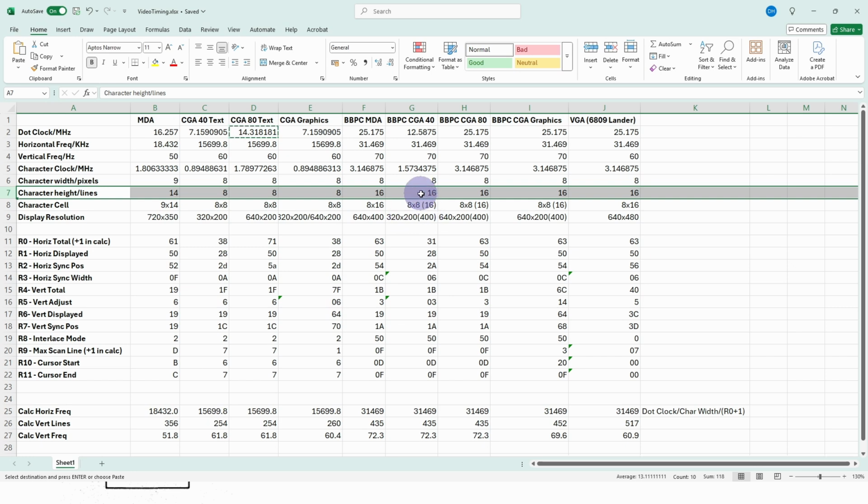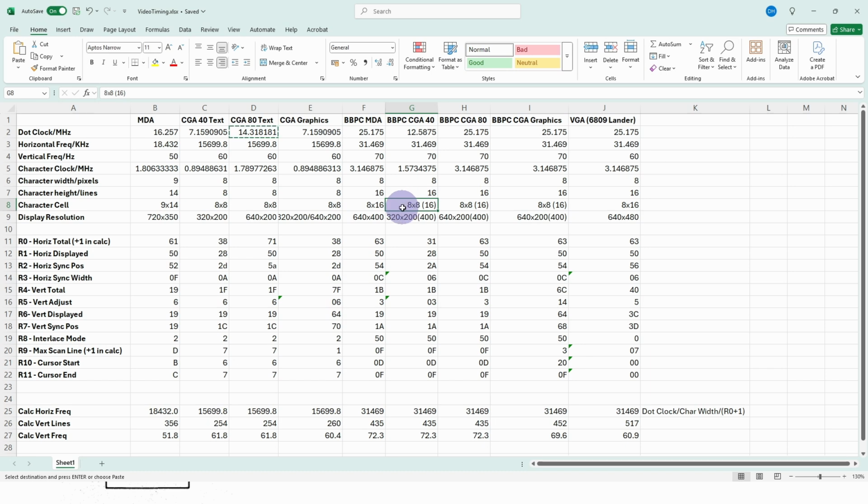By ignoring the RA0 line and only using RA1, effectively we double each line up. So although the ROM only has 8 lines per character, when they come out on screen they take up 16 lines because we're using the VGA output.